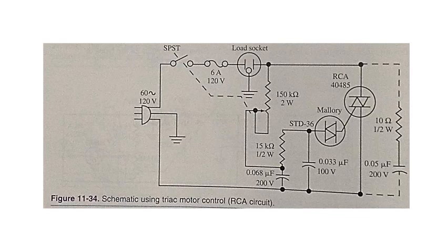When a universal type motor is used in industry, the series wound type is preferred. These motors are not used for heavy-duty purposes because of the large amount of sparking at the brushes. Commercial motors of these types are used for small fans, drills, and grinders.